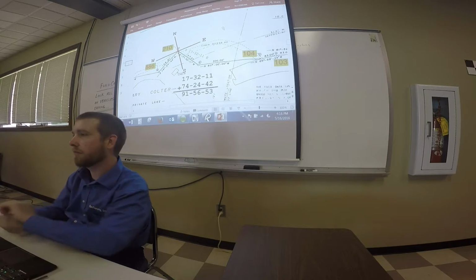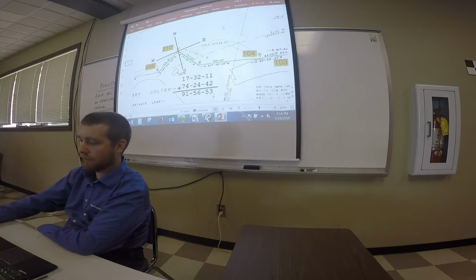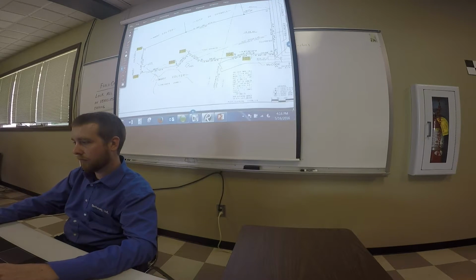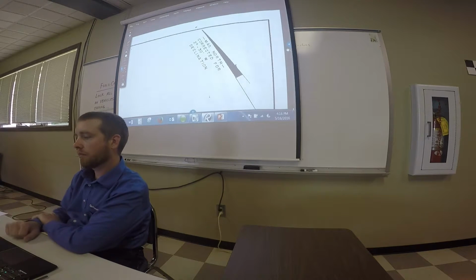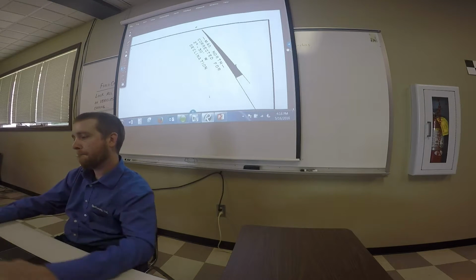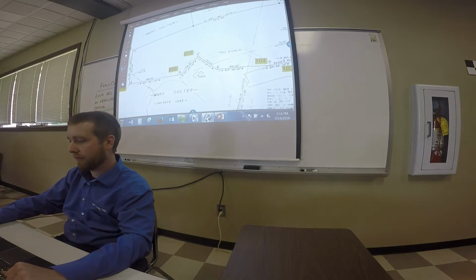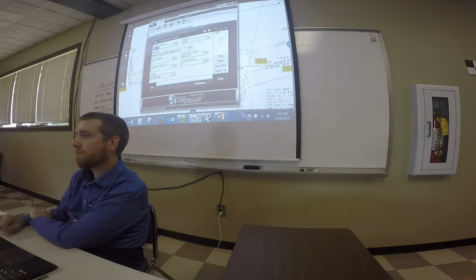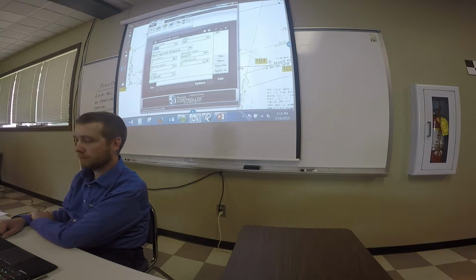You're traversing on a datum that is not the same datum as this drawing. Your north is different. You may be on state plane. You're not on the same datum this surveyor was on. But those internal angles, say he used a bearing to get his north, or a compass. Yeah. But that internal angle that you're calculating is correct. You're just applying that angle to your field data in your controller, right? Everybody grasp that? That's what we're doing right now. We're about to apply that angle and distance in our data that's in the controller and calculate new coordinates to stake out and put it in.